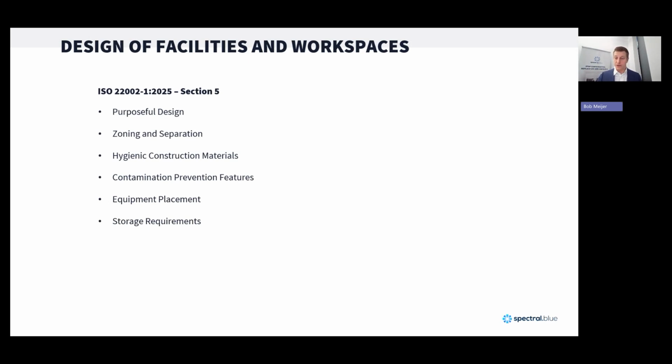Equipment should be positioned to allow easy access for cleaning, operation, and hygiene monitoring. And storage areas must protect materials from dust, condensation, pests, and other hazards. Segregation of raw, intermediate, and finished goods is required. Hazardous substances must be stored securely.